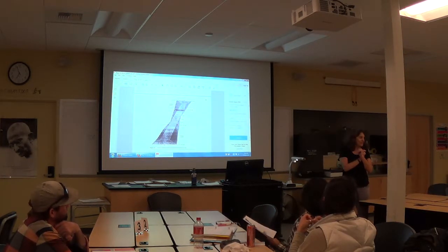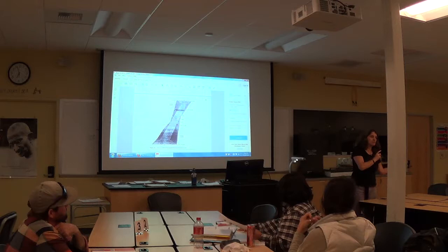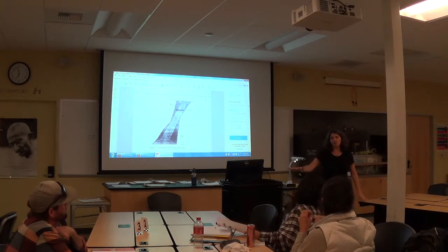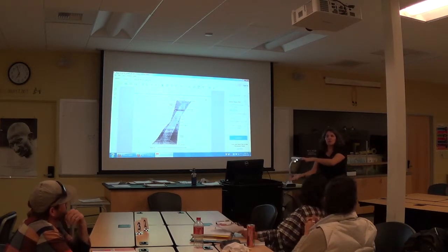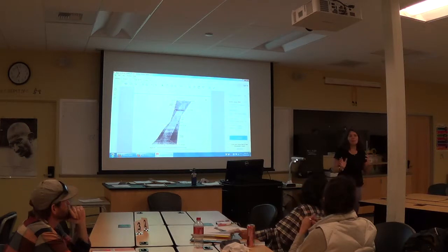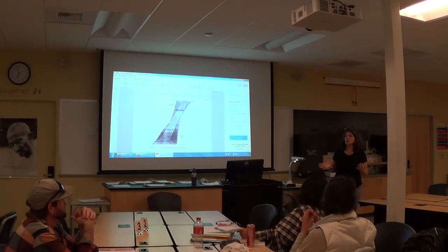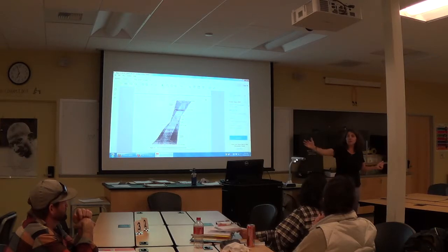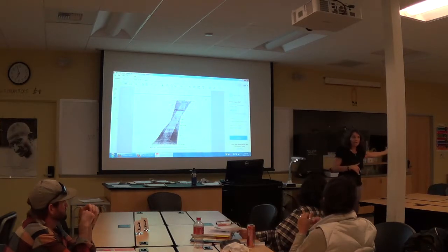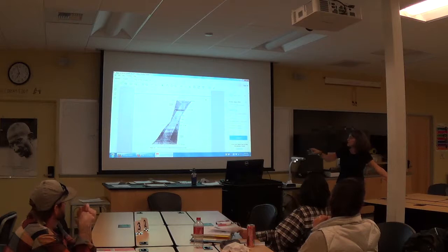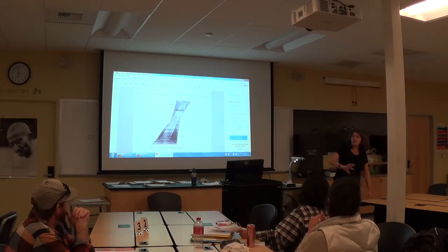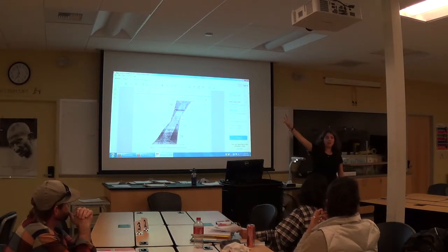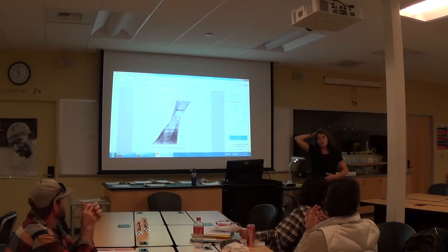Minimize cut and fill. You want to make sure that if you're taking soil away here, you fill it over here. If you need soil here, so it's all a balancing act, because you want to come pretty close to 0. You don't want to move it, and you don't want to move it great distances either, right? I don't want to take soil from station 10 plus 0, 0 and then have to move it to station 100 plus 0, 0, because that's another hauling charge. But it still saved me from dumping the soil somewhere.